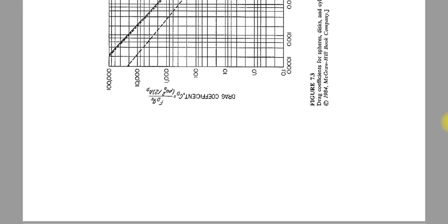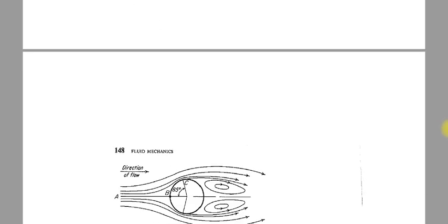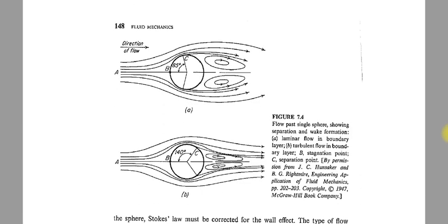the drag coefficient will be constant. For spherical particles it is 0.45. So if anybody asks what is the drag coefficient when the Reynolds number of the particle is 1000 to 3 lakhs, it is 0.45, constant. Most of the cases you have studied, you have to calculate the values in this region only. After 3 lakhs, the drag force, or drag coefficient, will reduce significantly.